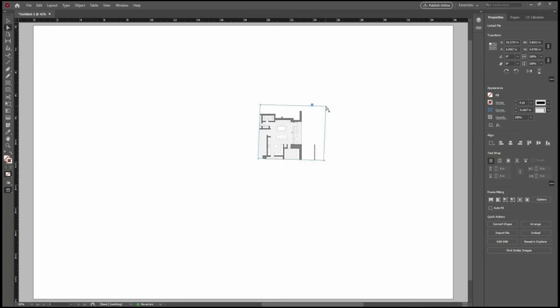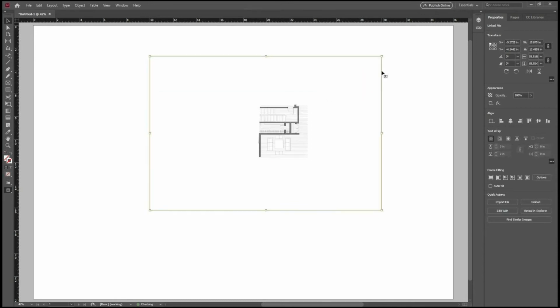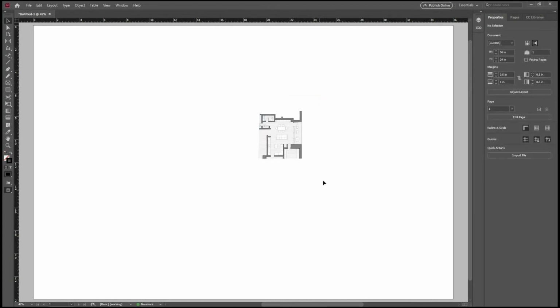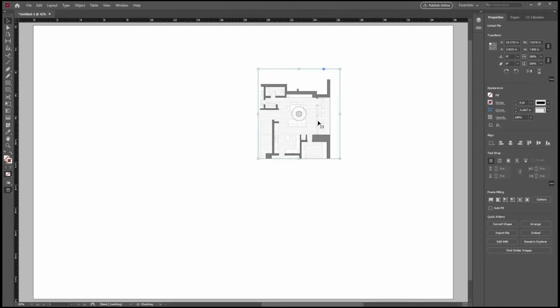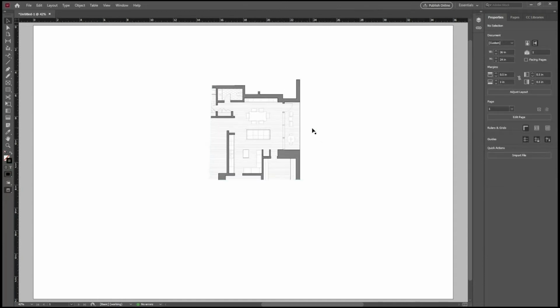There you see the little line command shows up here at the bottom. For example, there, you cropped the drawing. Choosing this arrow here, the selection tool, I can make that drawing bigger. Shift Control, I can make it larger, but it'll be inside of that cropped window. So ideally, you want to position your drawing on the sheet first and then decide what the scale is. Otherwise, it's going to scale it here. You can scale it using this tool here, for example.